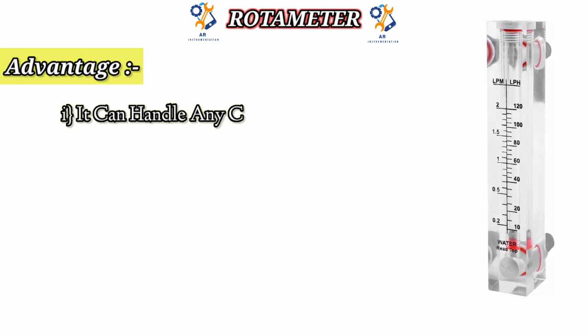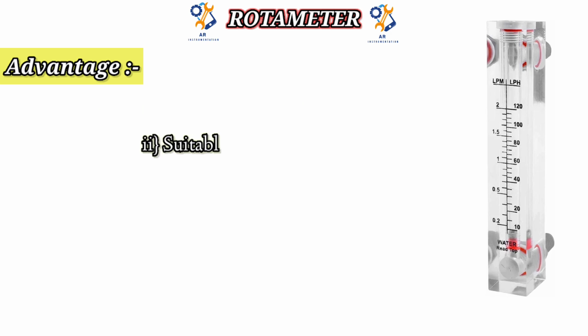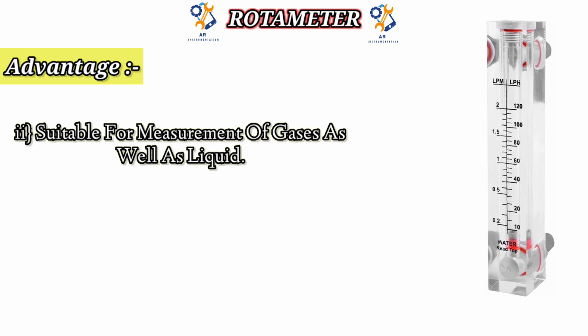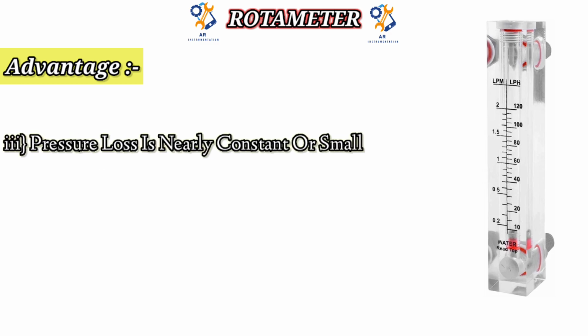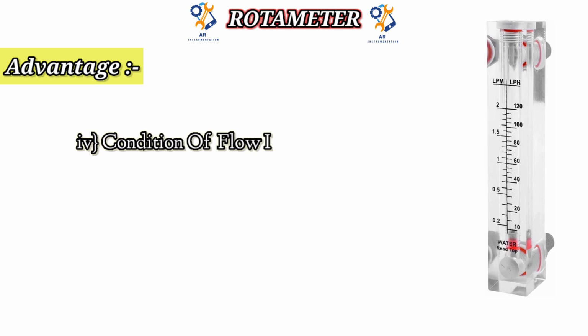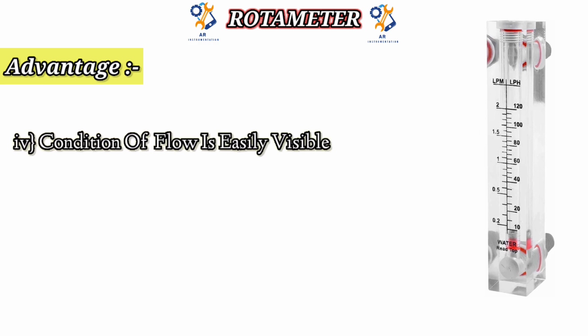Advantages and disadvantages. It can handle any corrosive fluid. It's suitable for measurement of gases as well as liquids. Pressure loss is nearly constant and small. Condition of flow is easily visible.